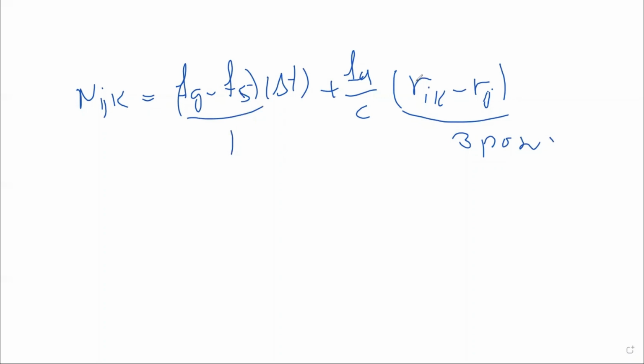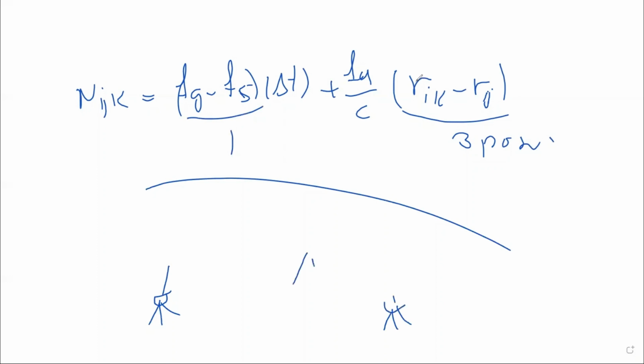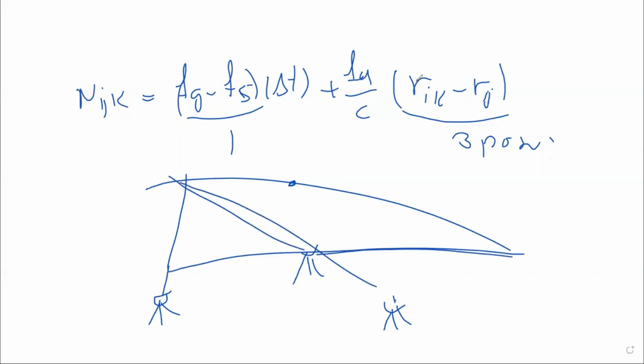But it is not only that, we can also have more positions. So for example, if we have antennas in different places, and we have one satellite pass over this area, and each receiver tracks the satellite over this specific time, they can determine their own position if they can receive the signal from the satellite. That's a multi-station positioning. That's also possible.